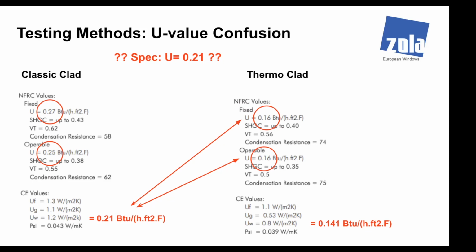And you can tweak the SHGC on the west facade if it's facing that way, and you could account for shadows from surrounding buildings if you're in the city, and you could do reflections on the back of the building if it's north facing, and deal with that kind of Passive House stuff, right? You're laughing. Yeah, been there. Reflective light off a skyscraper coming in the back of the building, being accounted for as heat gain in the back. You can do those kinds of things, and you can program it in with a 0.5 glass or a 0.62 glass or a 0.26 glass. We have 3 different glasses, so you can go up and down.